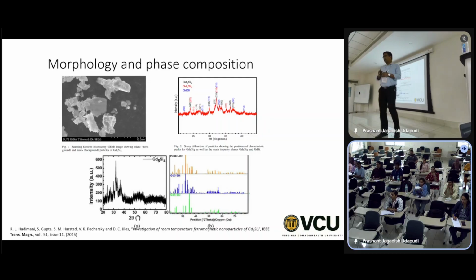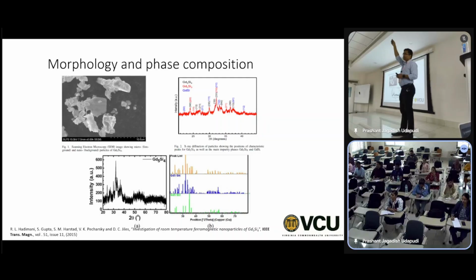What happens in a scanning electron microscope is you take a filament and apply a really large voltage to it. We're talking in terms of 200 kilovolts, and a very small current, but the voltage is very high. At that high voltage, the electrons start to come out of that material, so you get a beam of electrons.